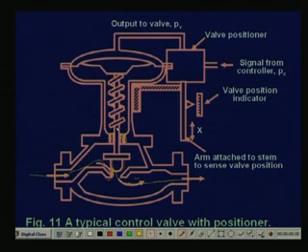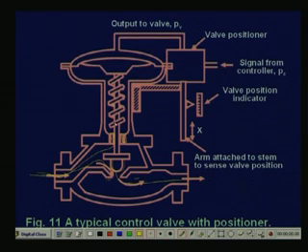This packing should be very tight in the case of a control valve, otherwise there is a problem. Why am I saying repeatedly about the packing? You see what will happen if the pressure of the liquid is high, it will go through this one, so that is not allowed. So, this packing should be very tight, right.